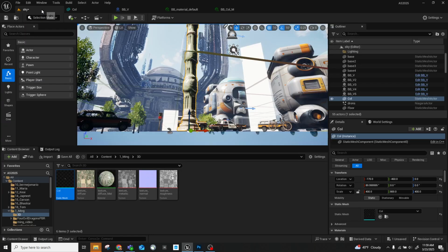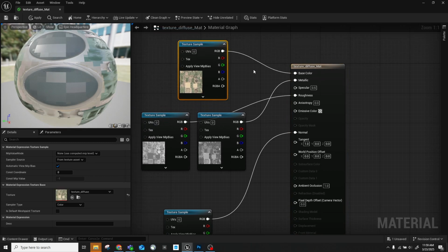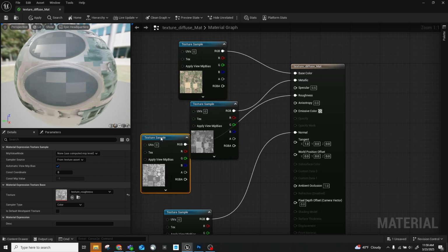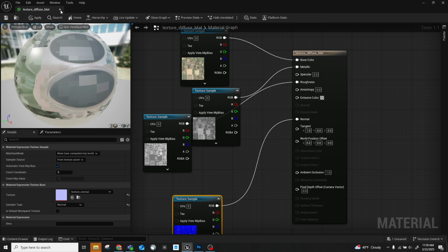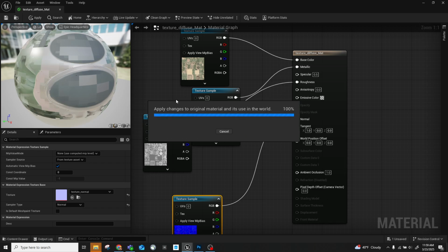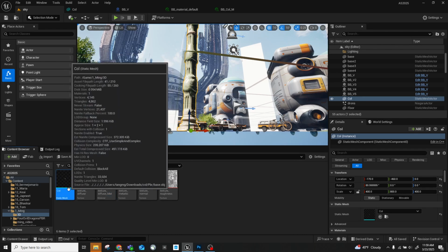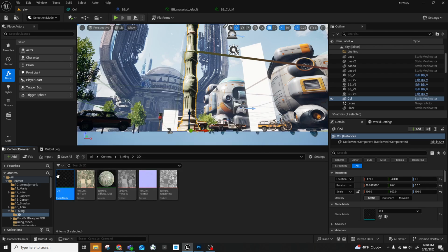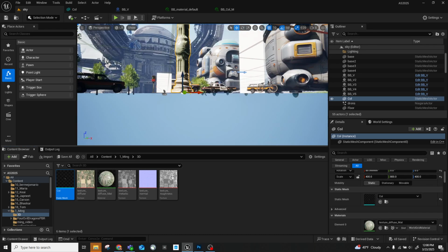So once you bring it in, you can create a new texture shader, and then you can load in these images. Base color map, metallic, and this one is roughness, and this one is normal. So once you reassemble this material, you can assign this material directly to this new column. Just make sure you rename it, because sometimes the file always comes with a default name. Unreal doesn't like the same name, so I renamed this from base to column. Yeah, that's how you see the material show up right here, and then you can just drag it in.